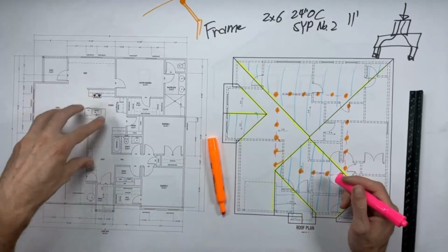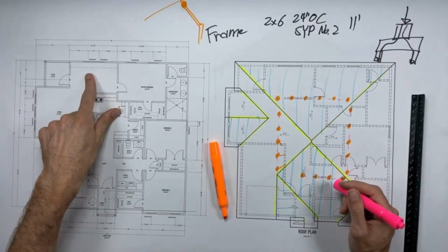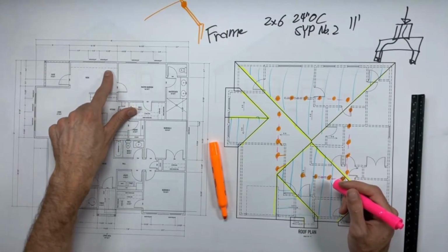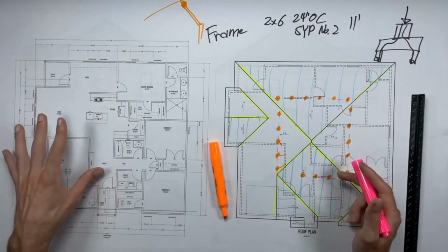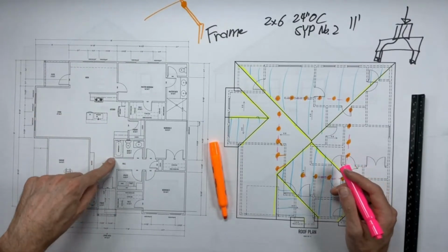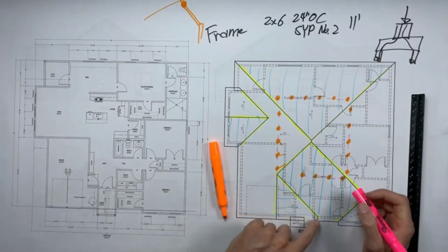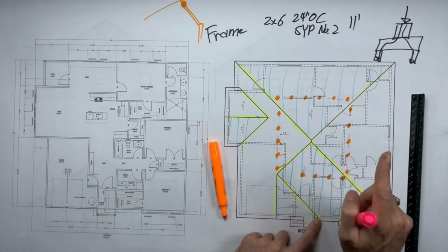I raised the whole entry and kitchen area up to 10 feet. That's what this line means in the back. That's a 9-foot plate, slanted ceiling, and then up to 10-foot ceiling right there. All right, so this is all actually 10-foot ceiling, which means this wall is 10 feet tall right in the corner where I need to brace. All right, and this roof plane starts at 9 feet. Important to keep that distinction in mind.